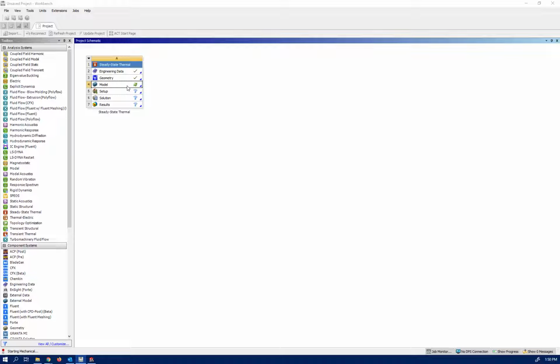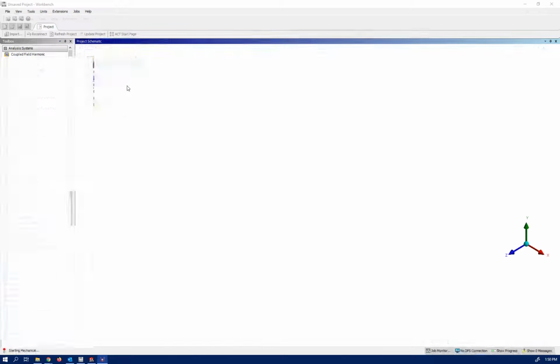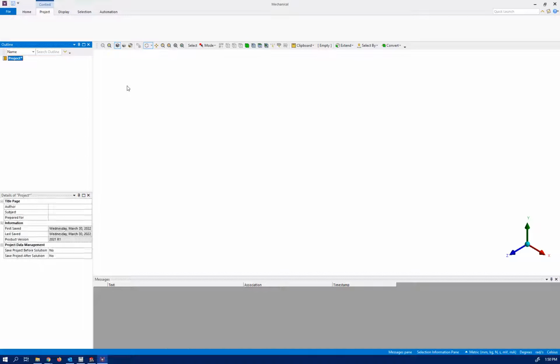Now I'm going to apply some thermal loads. Basically, for the thermal investigation, temperature is going to be the load. Because the geometry is a piston, I'm going to say the top side of the piston, for example, is, I don't know, 700 degrees, 800 degrees, because we have combustion happening there. So it depends on the type of engine. We may have different exact values for the temperature.